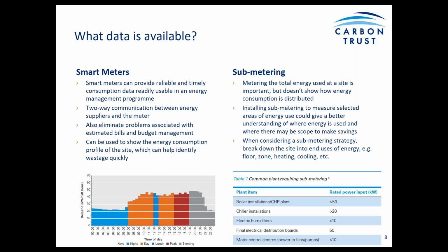Smart meters may also have export metering for microgeneration. So if you had any renewable energy systems installed at sites. And finally, they should also give an illustration of demand-side management options. So for example, if you have tariffs which charge higher prices for peak demand, but lower than average prices for off-peak usage, then they would encourage consumers not to use excessive energy during these peak periods.